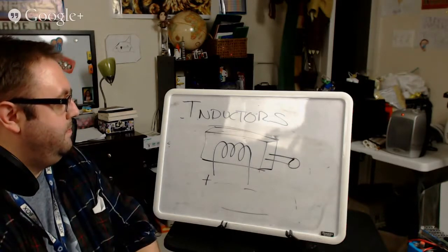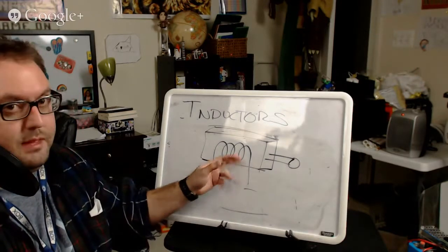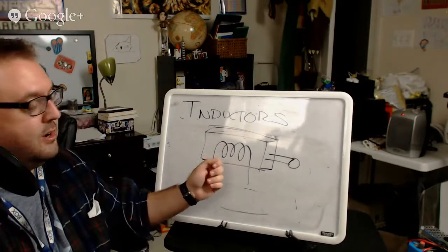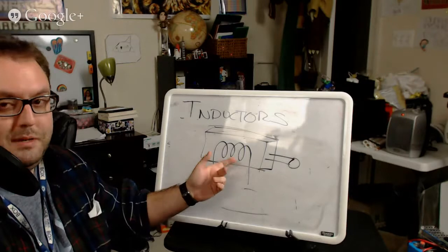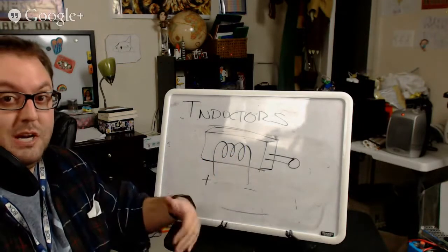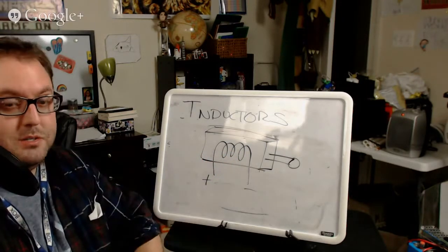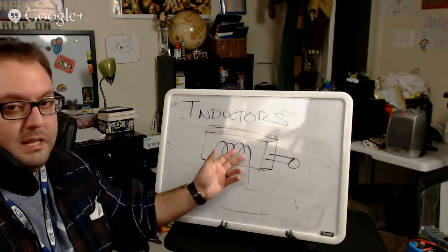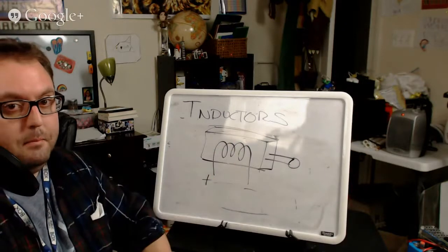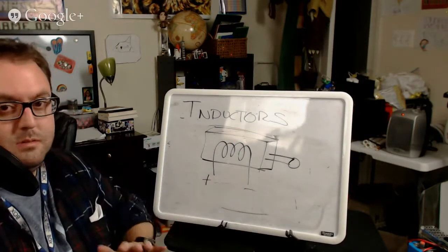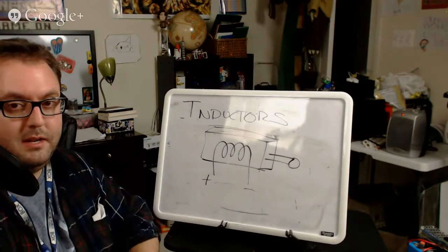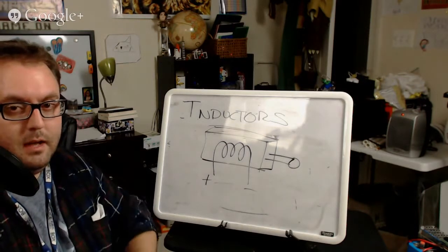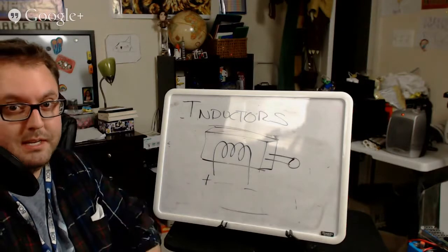A lot of times, though, the thing to think about with inductors, especially these kinds of things, is they need a lot of current. So you'll probably need an external power supply. You can't just drive it straight with your Arduino. Same thing with your motors, or else you'll fry them. So anytime you're dealing with motors, solenoids, before you just jump in and connect it right to your Arduino, think about it: you probably will need an external power supply.